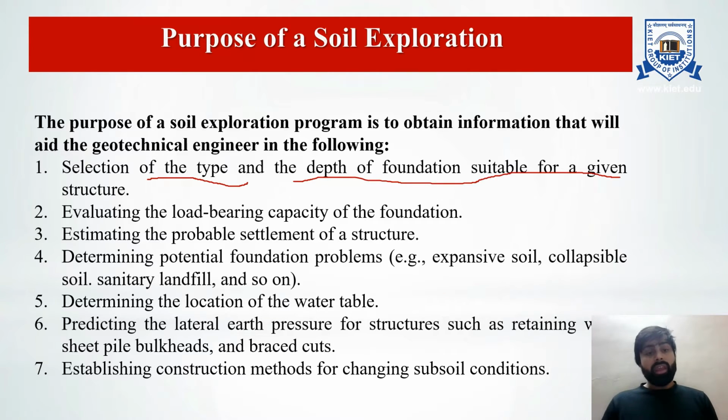The second one, evaluating the load bearing capacity of the foundation. The third one, estimating the probable settlement of a structure. And the fourth one, determining potential foundation problems, that is expansive soil, collapsible soil, sanitary landfills, and so on.